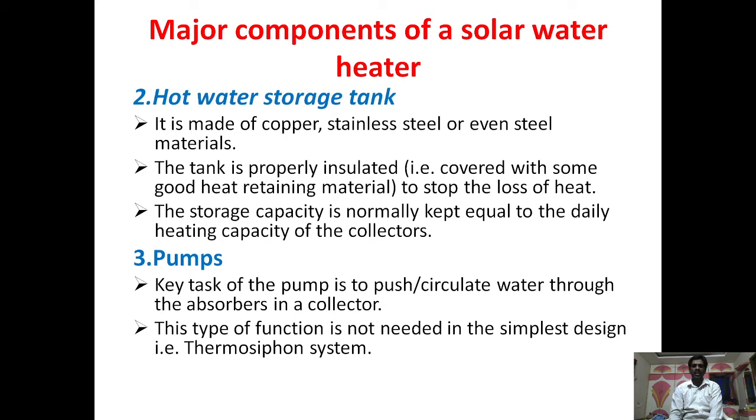Whatever material we use to cover the entire tank must retain the heat energy so as to avoid the loss of heat energy. And the storage capacity of the tank must be almost equal to the daily heating capacity of the collectors. So whatever water the collector heats must be equal to the storage capacity of the tank.